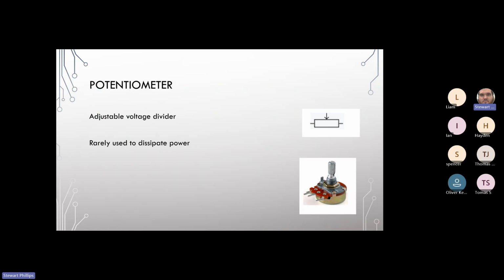They may come in double gang or triple gang versions, which provide multiple potentiometers on the same mechanical shaft. This allows the potentiometer to control 2 circuits at once, such as the left and right channels of a stereo audio amplifier. So have you ever looked at old school stereos and amplifiers with the knobs used for the volume control? They're actually potentiometers.